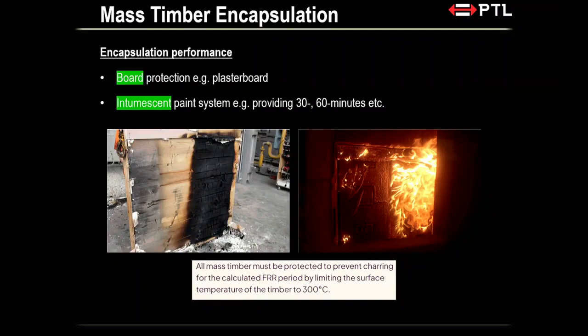All right, so let's talk about solutions. At some point, you have too much char depth. You've already gone past your first glue line, your layer is delaminating. The fire engineer comes and tells you that, hey, look, we need to get this under control. So you need to think about an encapsulation solution. One easy solution is plasterboard, right? Board protection, cover up your timber area.